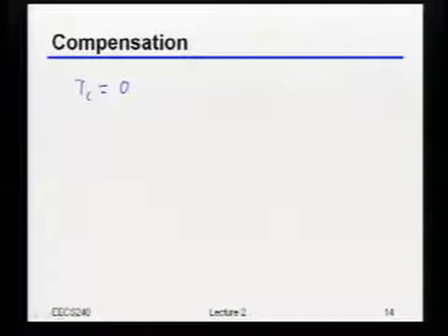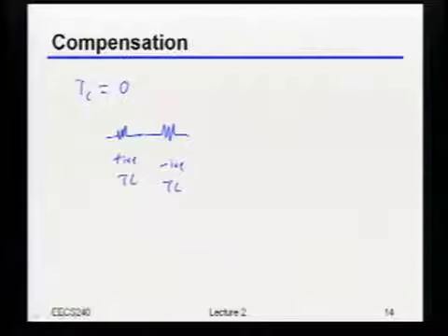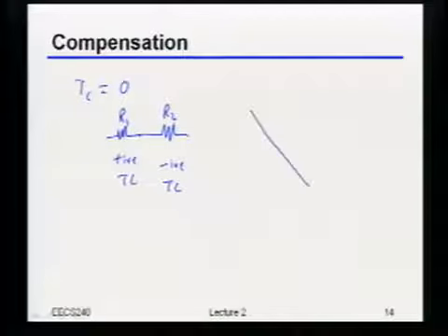It's a hack. Could you combine N plus and P plus poly resistors? Yeah. Right? So if I get one thing that has a positive temperature coefficient, and then I have a second thing that has a negative temperature coefficient, and I just put those two in series, I basically get something like 2 equations and 2 unknowns, right? So I figure out how big do I make that first R and that second R such that the total resistance is the resistance I want, but that the temperature coefficients of the two of them happen to just cancel each other out, right?